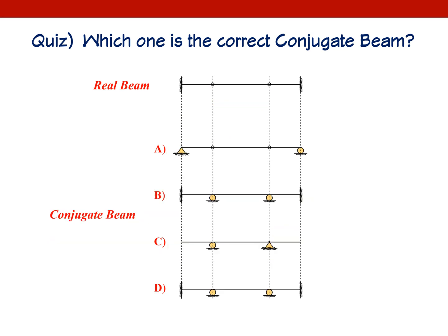Okay, one more quiz. Which one is the conjugate beam for this real beam? Let's go one by one. Again, support condition: fixed will be free. You already got the answer? Okay, let's check the rest. Internal pin will be internal pin support.